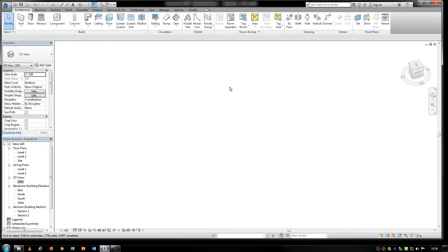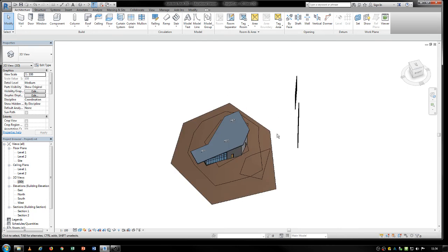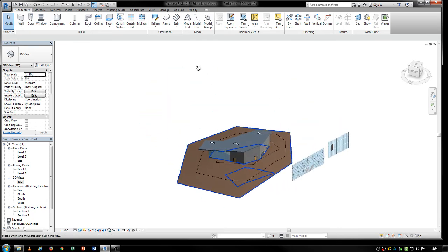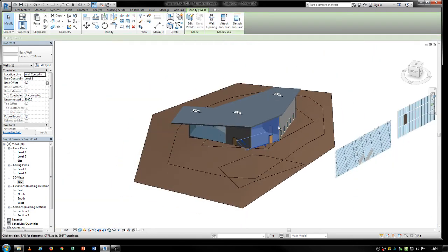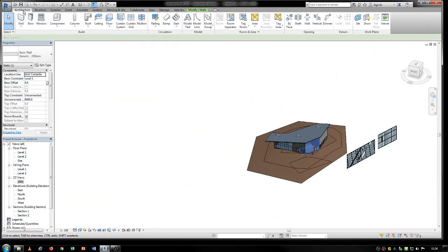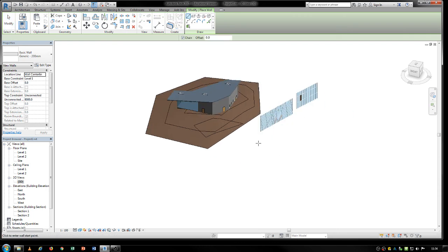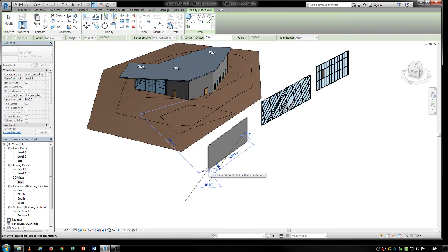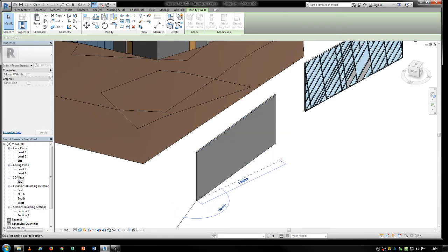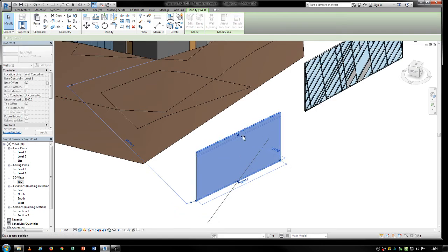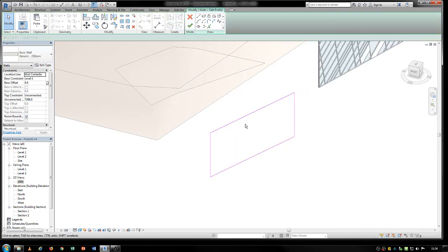And then the last thing to show in the tutorial today, and then after this I'll go to your individual questions, is how to deal with a few wall editing tools. So kind of answering Cassidy's question. If you have a wall here, there are a series of things you can do to it. You can move it around, you can change the height, you can change the type and all that kind of thing. You could also edit the profile of a wall.